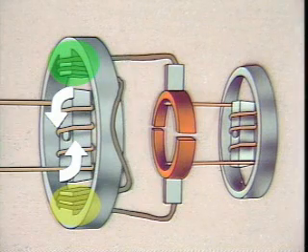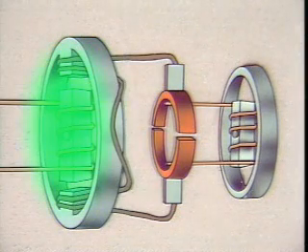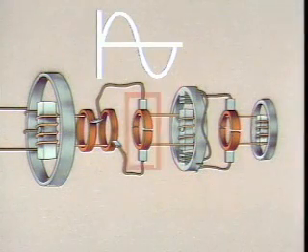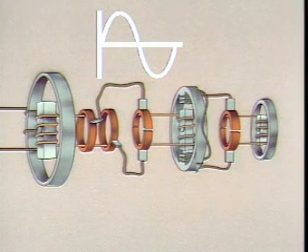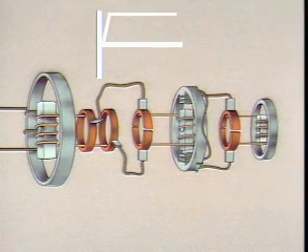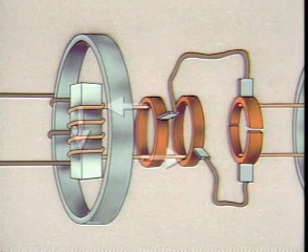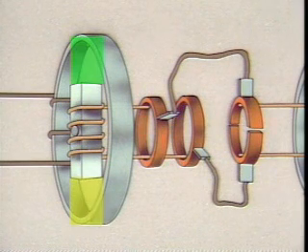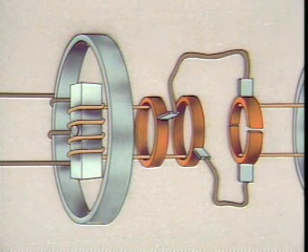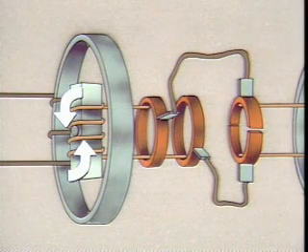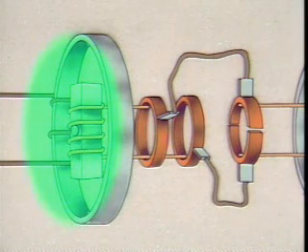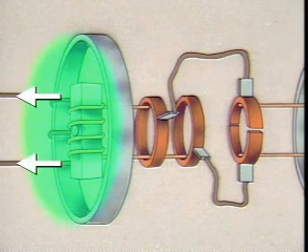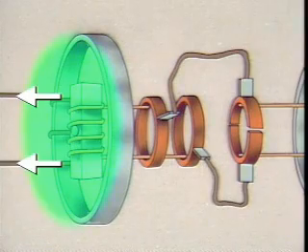When the shaft turns the rotor of the DC exciter, a moderate voltage is induced in the rotor windings. This produces an alternating current at the exciter commutator. The commutator converts the AC into direct current. Now the direct current flows through the slip rings of the generator and through the rotor windings, creating a strong magnetic field. And finally, as the generator rotor turns, a large amount of voltage is induced in the generator stator windings. It is this voltage that goes through the transformers and is transmitted to consumers through the power grid.